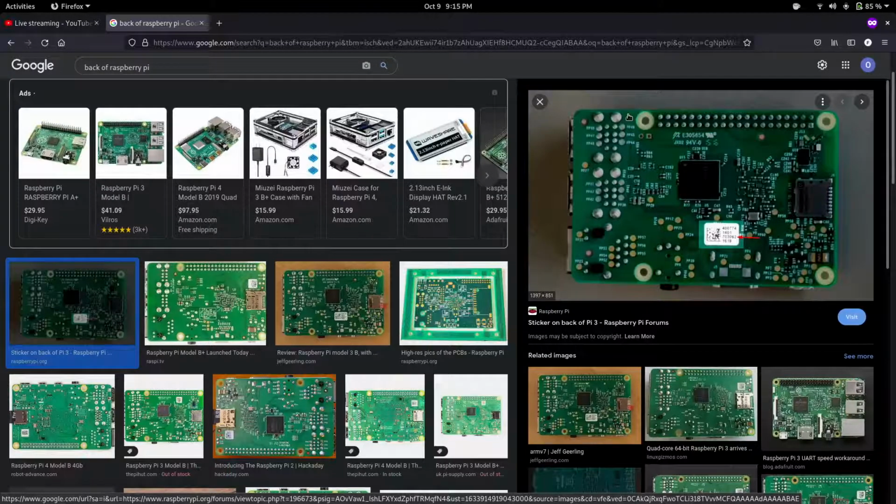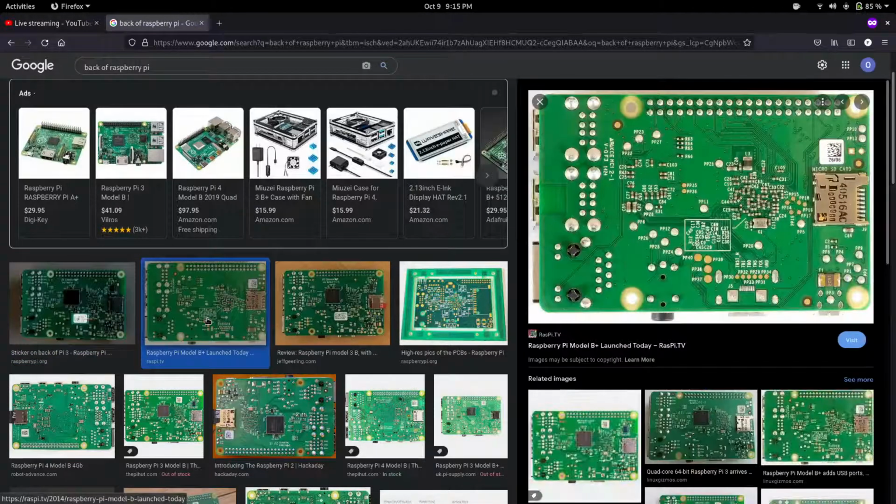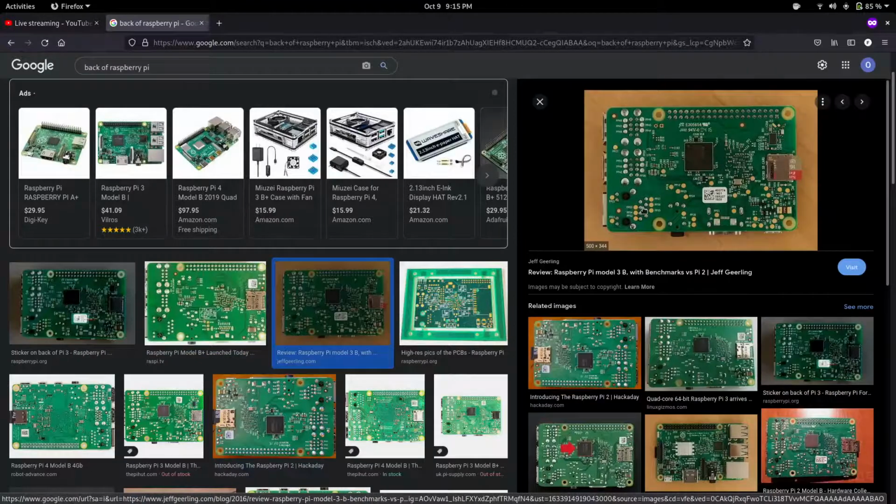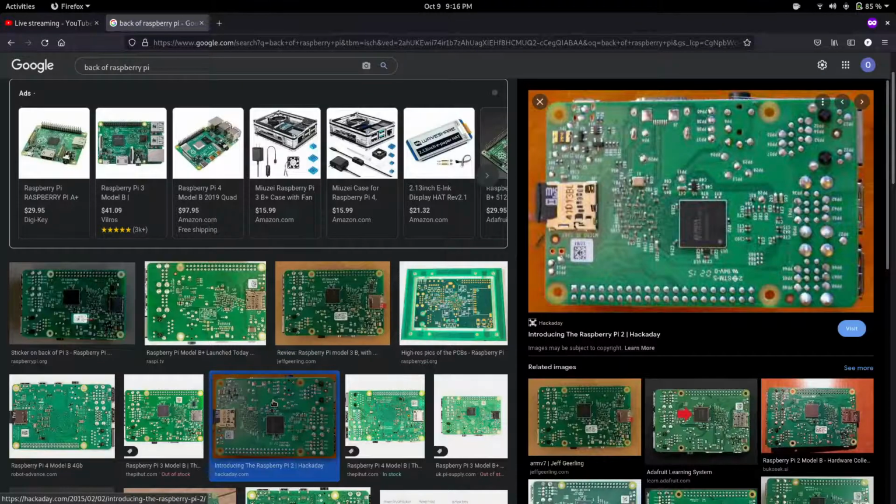But USB ports experience repeated stress when you plug them in and pull them out. So very often connectors like that are going to be through-hole for extra strength. Also, it might make it easier to sink a lot of current. It's really a decision you have to make based on how much space you have and whether you want to be assembling your PCB by hand.